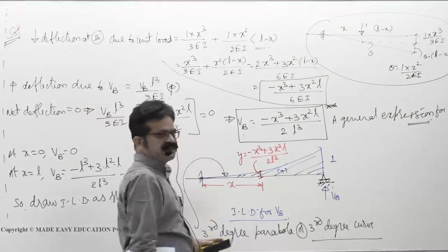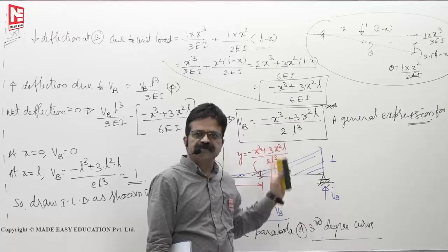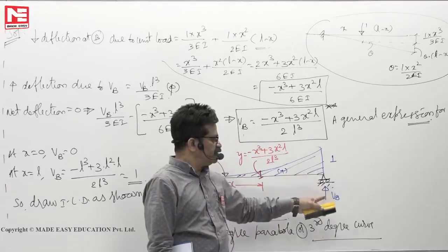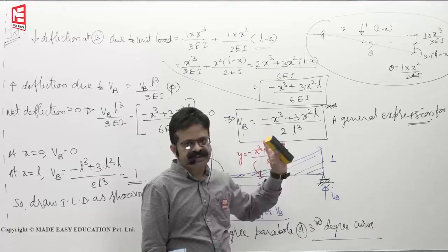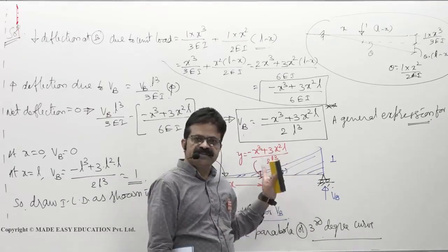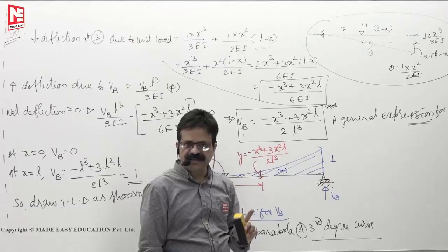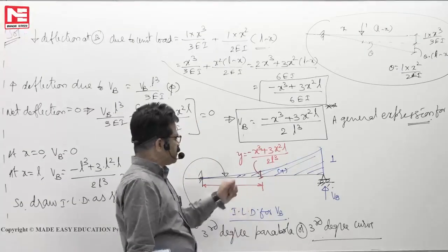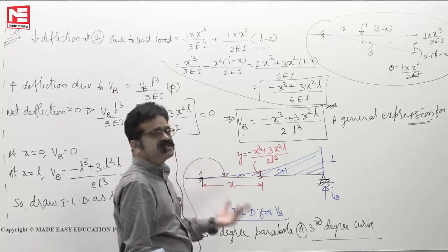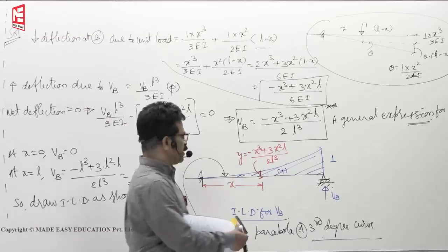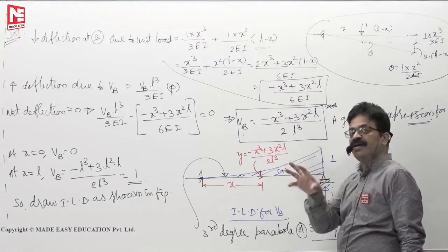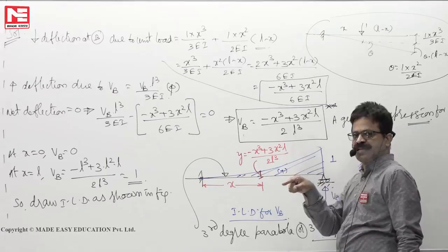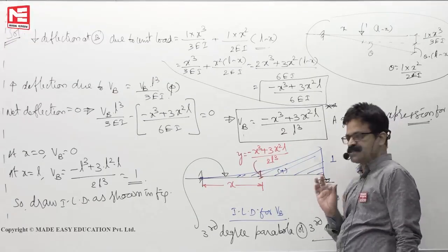Okay, that is the first observation. For indeterminate structures like beams and frames, ILD for reaction, shear force, bending moment, all of them are third degree curves, whereas for a determinate structure it is a first degree curve. And this one, Muller's principle, we can also apply here to draw the ILD, the qualitative diagram. How the shape looks like, you can get it from Muller's principle.